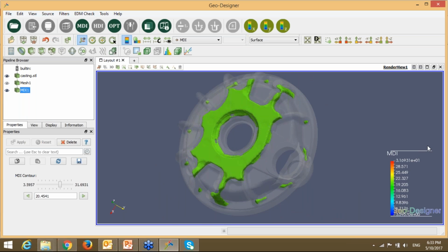Okay, we have one more question here from Sandeep again. Is it taking reference of pouring temperature and chemistry while deciding the last solidification point? No, it is not taking any consideration from chemical composition, solid-liquid temperature, or pouring temperature point of view. What we are analyzing is purely based on the mass of the casting part.